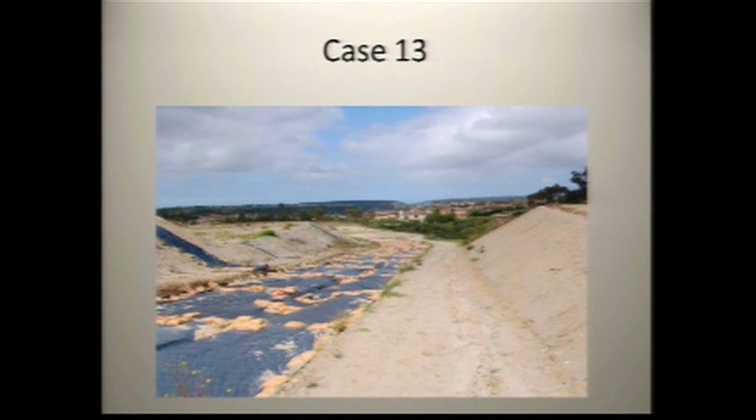Yes, exactly. The Visqueen salesman was successful at this site, and I think his kids are all the way through college probably. But what I want to point out is, you see how there's kind of a dip in the visqueen. It's the same problem that we had on the previous slide. They put down visqueen, which was a good attempt, but it just gullied right under the visqueen. And the same thing happened at this site.